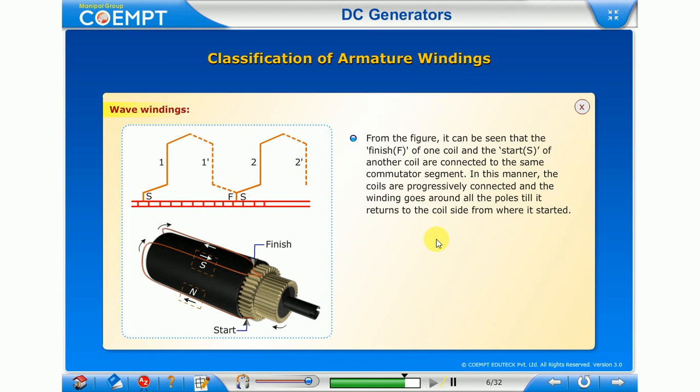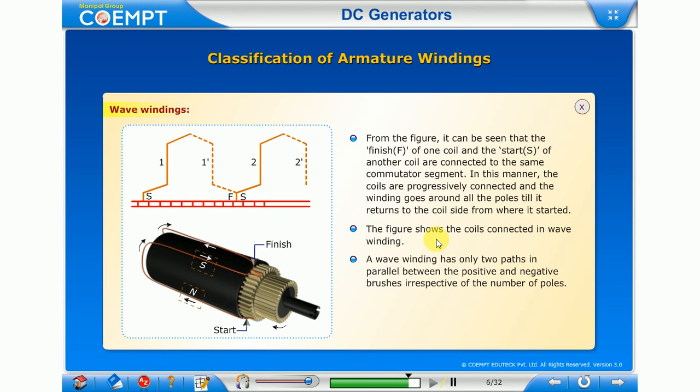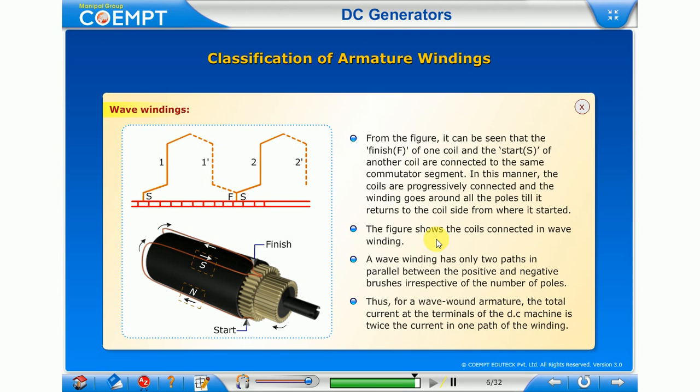Two collecting brushes of carbon or copper press against the commutator segments. Their function is to collect the current induced in the coil and to convey it to the external load resistance R. The rotating coil may be called armature and the magnets as field magnets.